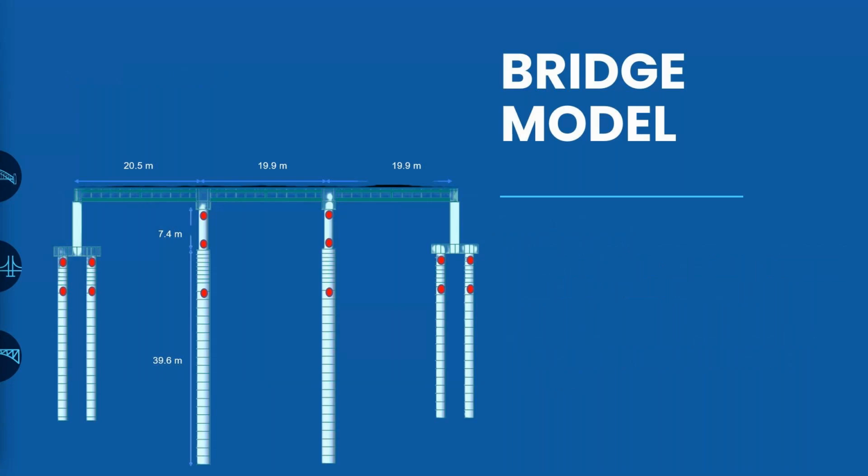For an engineer, it is very important to first specify the location of the plastic hinges, or the probable plastic hinge location in the structure, to actually assign the plastic hinges at that particular point, right? So it is very important for us to know at what locations the plastic hinges could form. For this particular structure, I have considered the plastic hinge locations as shown.